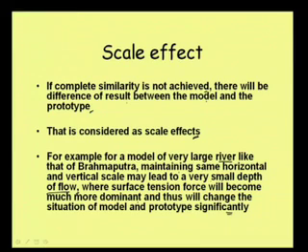I was saying large earlier, but it should be very small depth of flow, as already explained. In that case, the surface tension force may become quite significant and change the situation of model and prototype significantly. This sort of thing we refer to as scale effect.